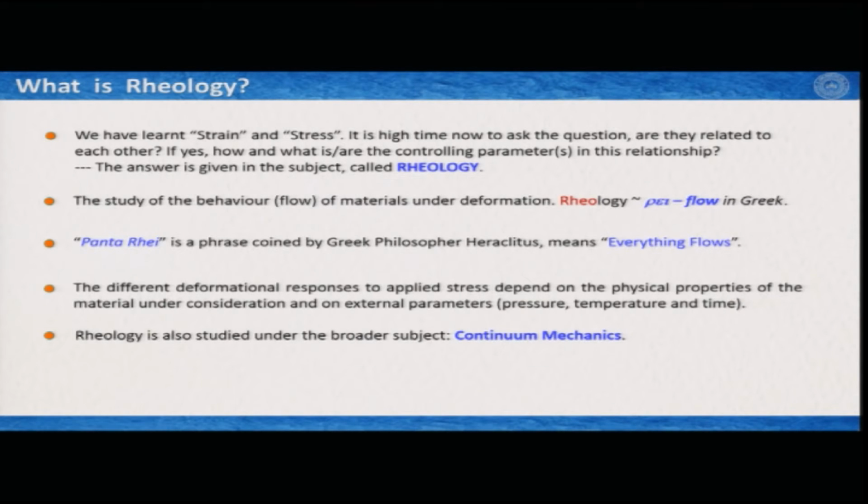And the study of the relationships between stress and strain is the study of rheology. That is not only important for our subject, but for most subjects, particularly in food industries and so on. So, if I have to define rheology, it's very simple. The second point narrates the definition of rheology. The study of the behavior or flow of materials under deformation is rheology.